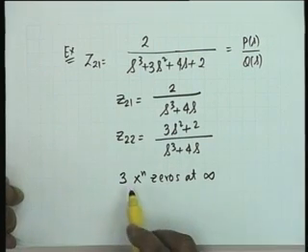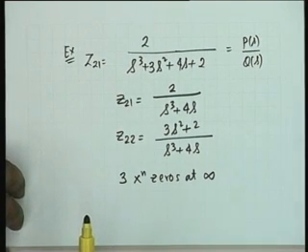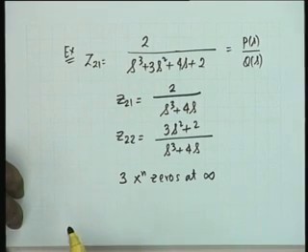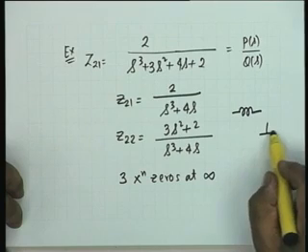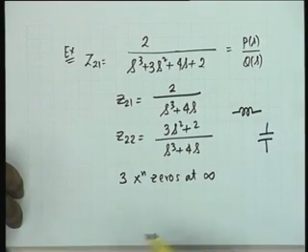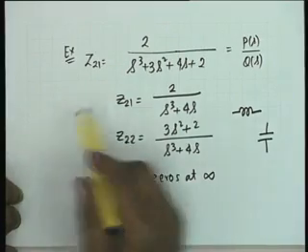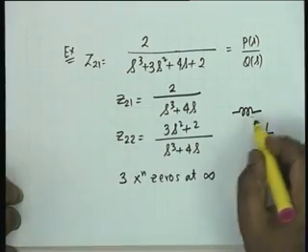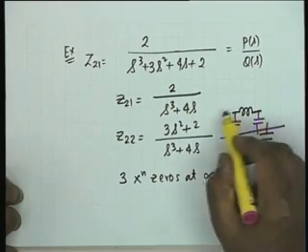Obviously, if there are transmission zeros at infinity, then it shall be either a series inductance or a shunt capacitance. In a ladder network, it shall be either a series inductance or a shunt capacitance. And we argued that in this case, in order to realize 3 transmission zeros, our structure must be of this form: 2 capacitors and 1 inductor.